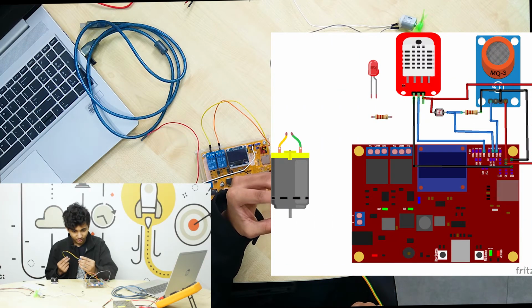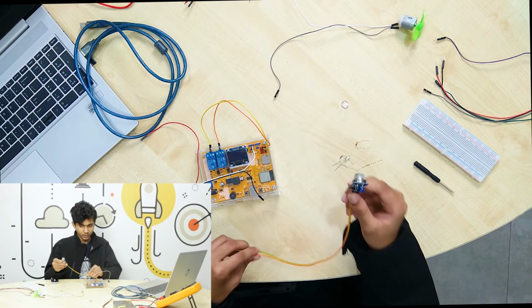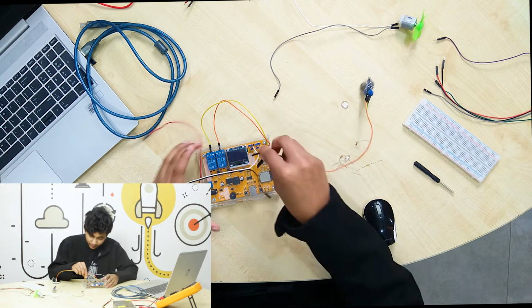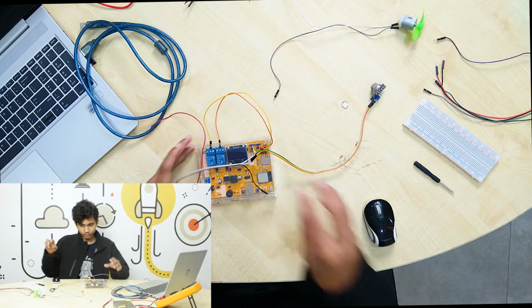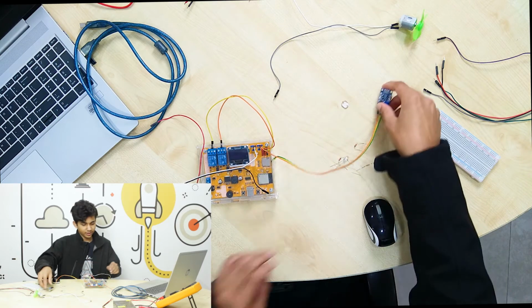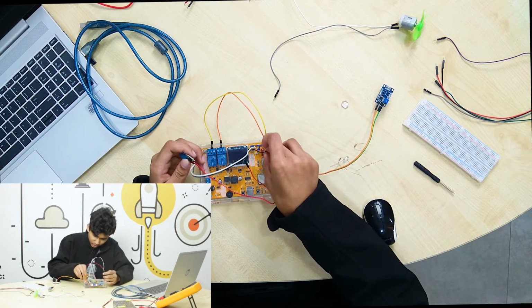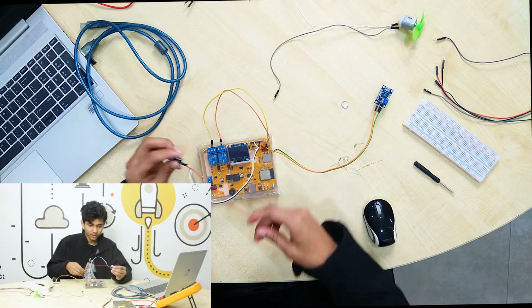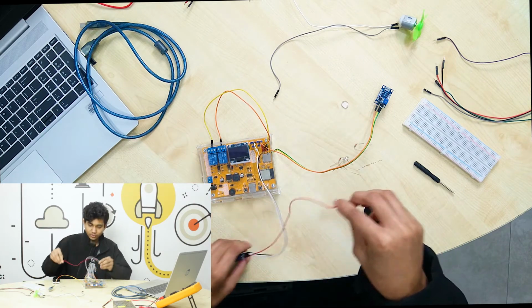Alright, so the circuit, we have an analog output. Let's see where the smoke sensor is connected. It's connected with 39. Now that we have the data pins, let's connect the GND, the ground, and the VCC. It's actually pretty easy this way, because we just need to connect these already known pins. So let's connect it.